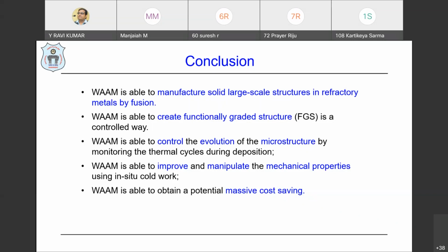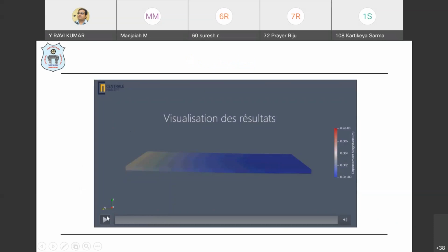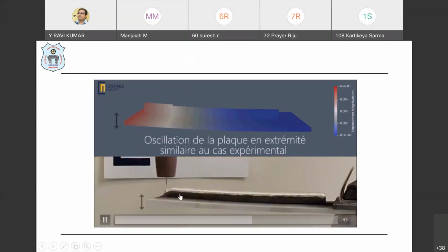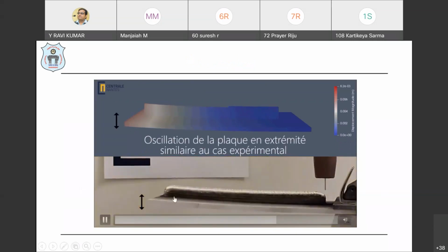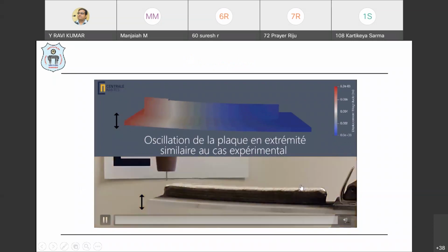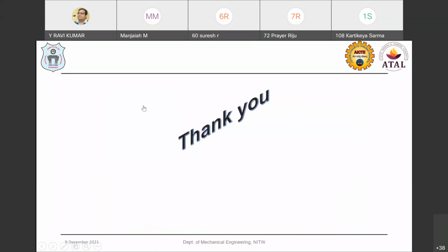And you can see we also simulated how the stress and deformation take place. When it is welded under one condition, you can see the welding and layer deposition taking place. If you are not welding under another condition, here we have a lot of thermal stresses occurring. Here we have a lot of deformation. The stresses are going to occur in that component.